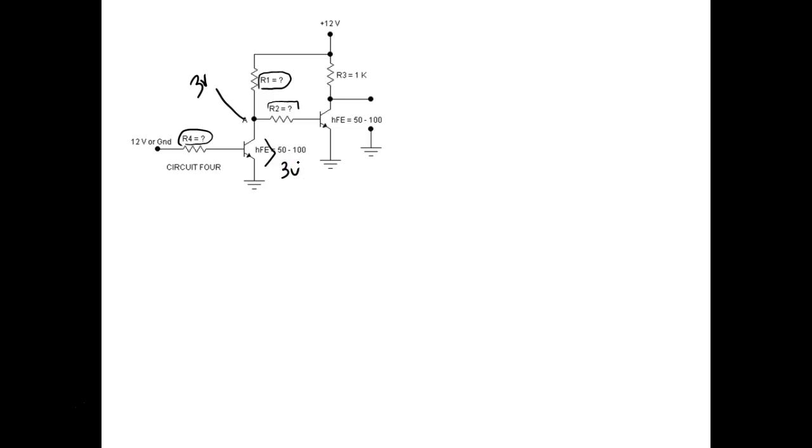Why do I know that? This guy, we're working on this one right here, Q. Yeah, you got 3 volts on the collector. So if you got 0 volts on the emitter, you got 3 volts on the collector. It means that transistor's got to be dropping 3 volts. So I can't use that transistor right now.